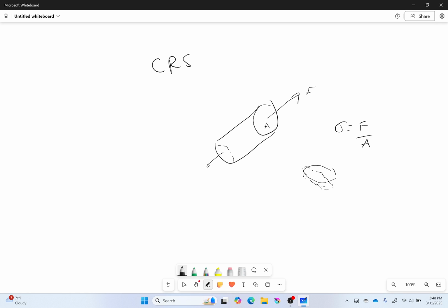That is my plane from earlier problems, the triangular plane for a face-centered cubic. Maybe this is aluminum we're pulling on, and that's that plane right there. Now I'm pulling along this, but my normal is over here. That's my normal direction, so it's at an angle right there.